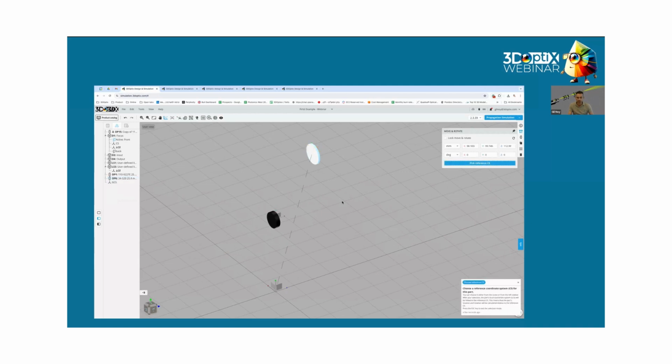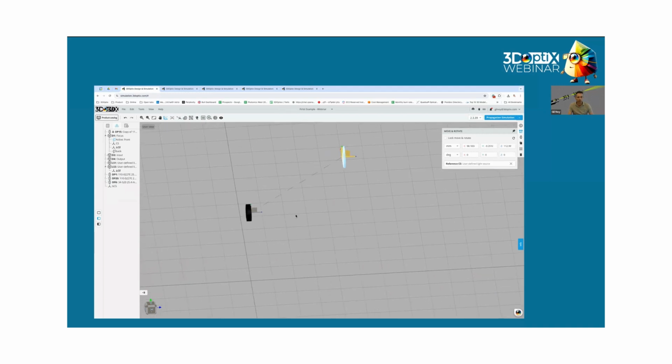This is the instruction. And you can see that all the coordinate systems that exist in the canvas show. All I need is to select one of them. And then you see that the dotted line changed. Now here I have another button. This is reset. It would reset all the parameters in the move rotate window. And then on the Z axis, I would put 100 millimeters, and I would get it straight on the same axis.